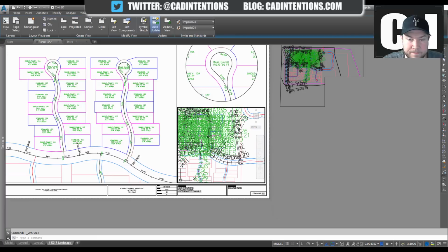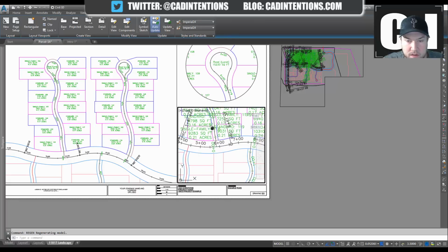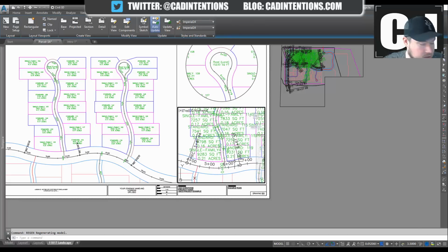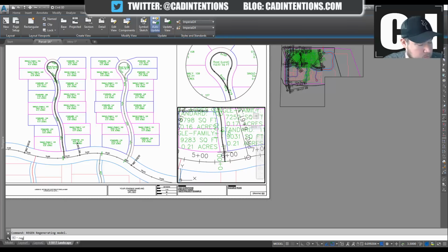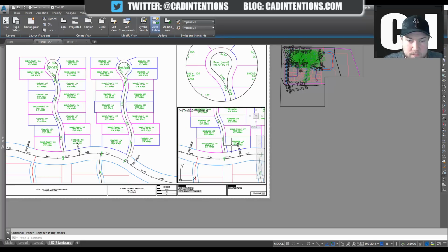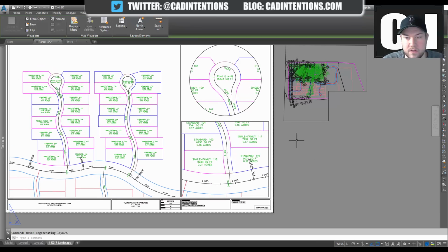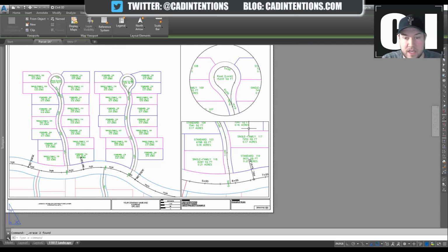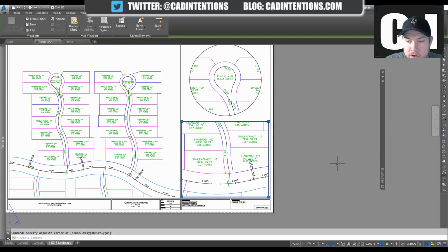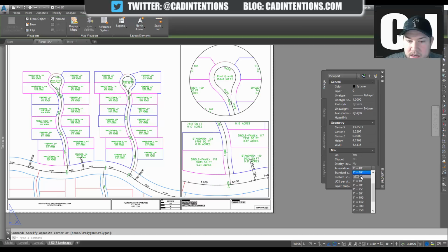And then over here, we're going to show information right here at this intersection. So I'm just randomly zooming in and out here. You're going to want to use actual scales, and I've got a couple of videos on that, but the gist of it is you select your viewport and then you can change the scale here using the annotative scaling and/or matching it to the standard scale.